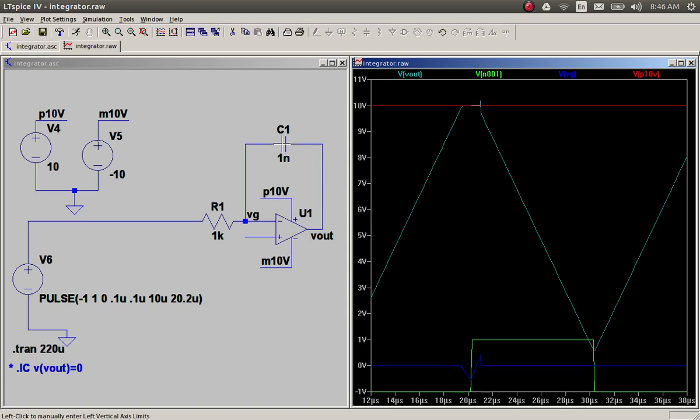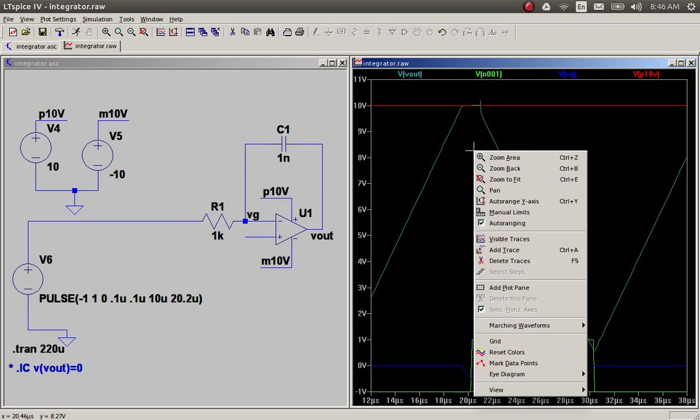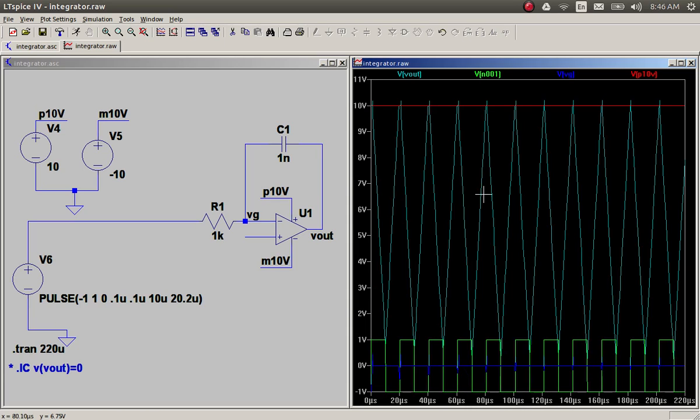So it's not able to use the fact that this could have charged more, so it gets clipped there. So this is an example of where a waveform gets clipped. So some of the ways you can encourage Spice to give you what you expect is to force nodes at some points. So that's what we have done. We have forced the output to 0.